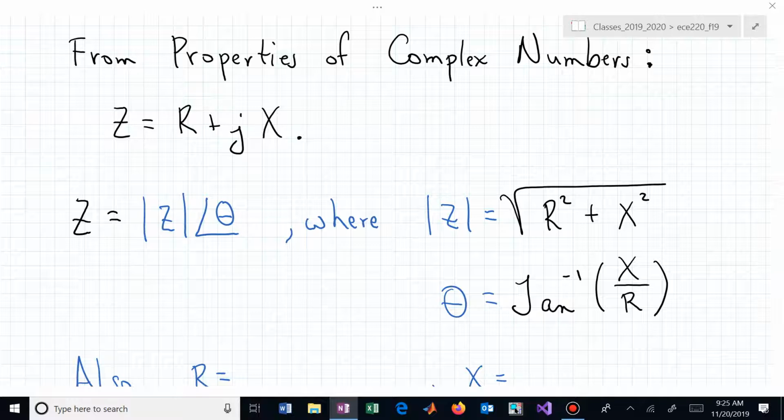If you had a positive angle, what do you know about that box that has R's, L's, and C's in it? Is it inductive or is it capacitive? If your angle is positive, it's inductive. If that angle of your impedance is negative, then it's capacitive in nature.